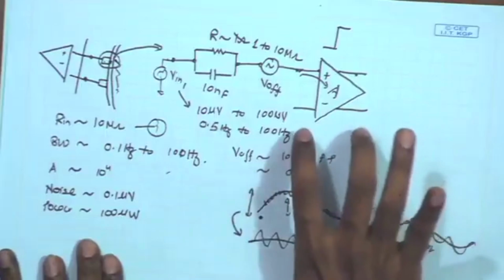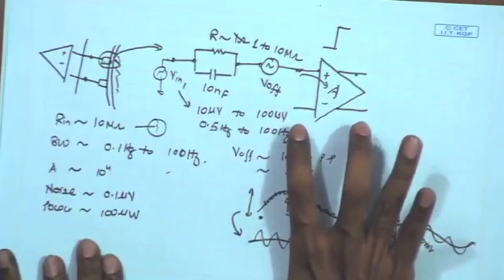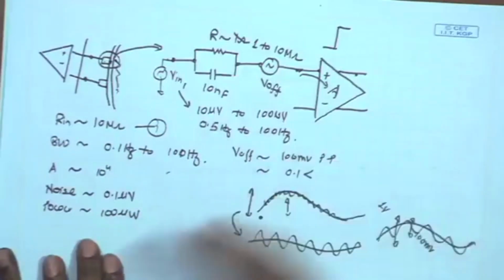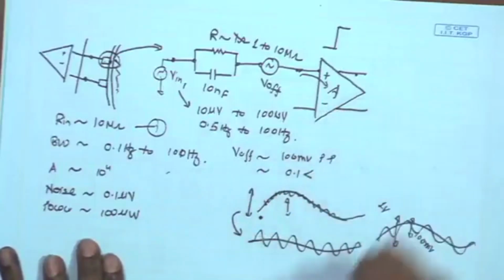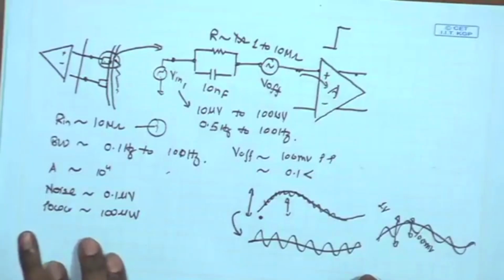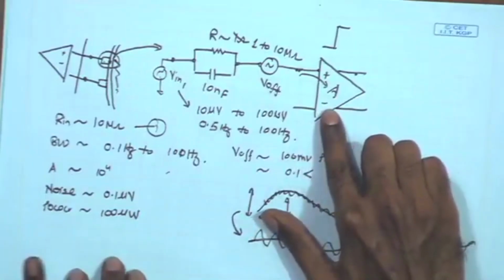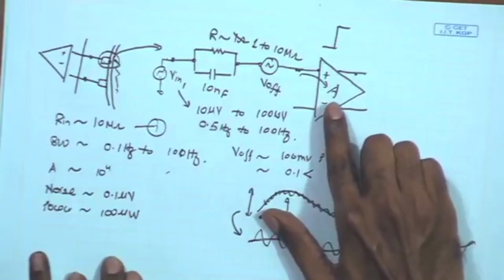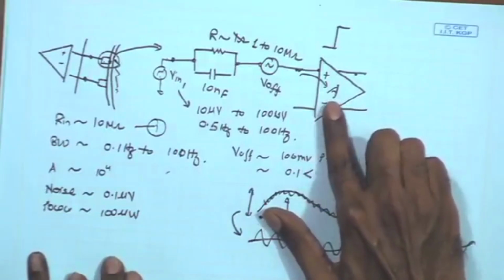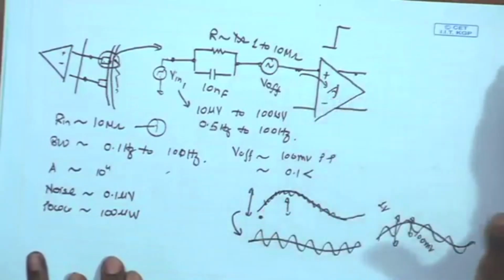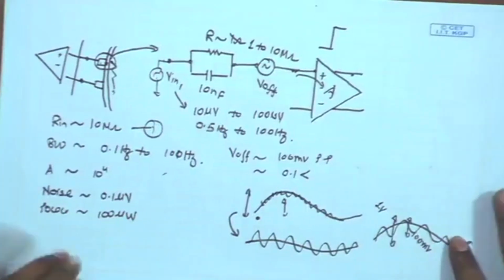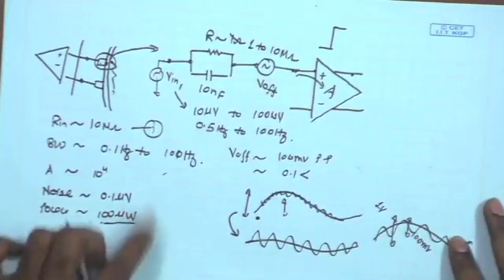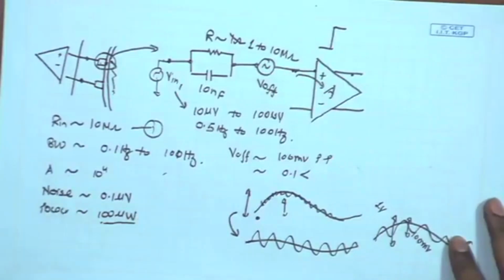We will see that majority of that power dissipation can be taken up by the front end amplifier, because there we have the serious noise constraints, because this must be low noise, and as we will see during the noise analysis of our transistor level circuits, the low noise criteria translates to requirement of sufficiently high bias current, and as a result this is going to be our most power hungry block. Beyond that, there are of course other units like the filters and the ADC, which can also consume significant fraction of the power. So, this entire power budget needs to be judiciously divided among those multiple stages.